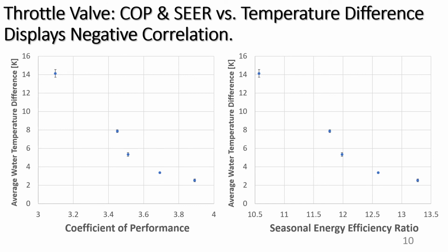This rating would not be acceptable for an air conditioning unit in the South, as none of the SEER values reach 14. While the throttle valve was less efficient than the orifice, the error tended to be much lower, as seen by the barely visible standard deviation bars.